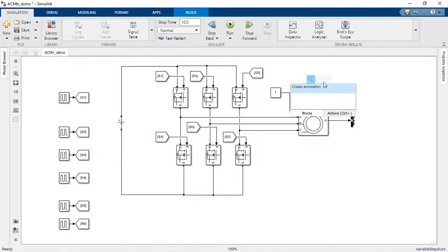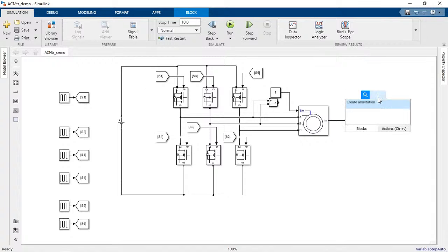Now again a voltage measurement block. Just connect a voltage measurement block. Again here in the basic simulation, you can use one DC power supply. By adding two split DC power supply filter capacitors, we can get a neutral power supply also. Take a scope.